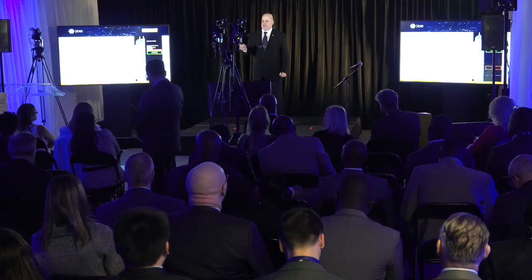Go ahead. Morning. Would it really be worth giving the pilot the option of deciding what will be his optimum route? Or would that not be more appropriate for the air traffic controller to decide? So this is a two-way system. This is a super question. There are two sides to this. The first side is that ATC actually provides what routes he is making available to the pilots to choose from, and the pilots choose from that. So the system knows which routes or partial routes are available, and then it provides that to the pilot.